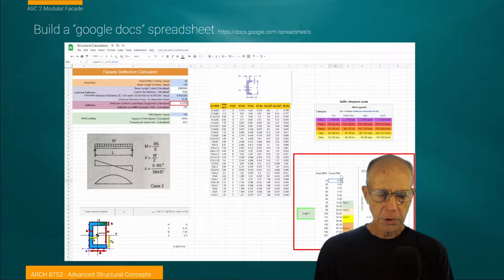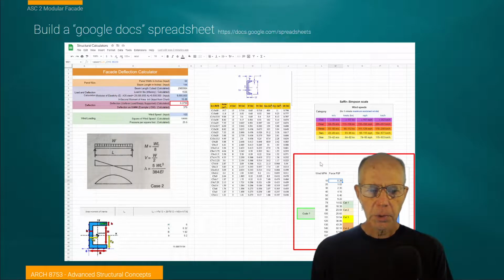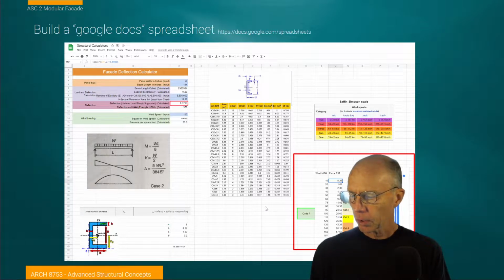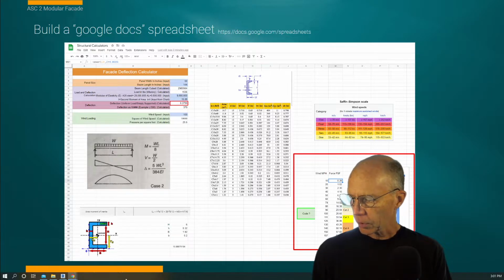As a matter of fact, I can show you just at the bottom corner of this one behind my head, we have a wind speed that develops that 30 pounds per square foot load. And that's in the category 2 or category 3 storm rating, and that I've outlined as being in the code area where the governing bodies say we need to design for wind loads in excess of 111 miles an hour. So anyway, let's now take a look at that spreadsheet and how we'd generate those kinds of calculations.